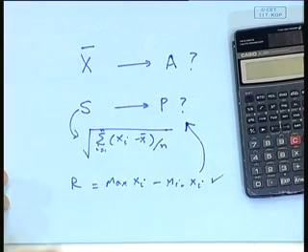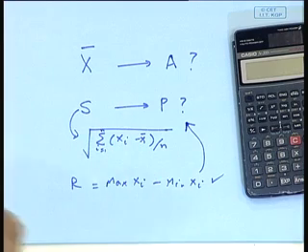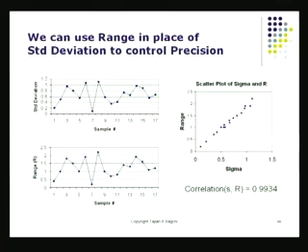What is the link between these two? You might just say then, is there a correlation between these two? Let's look at some real data. I have on the screen here, the top chart is the S chart, the standard deviation chart. I've got my samples here, I've got the values there. For the same data, I calculated range, and they are like this. And notice how close these two are. In fact, if you do a correlation plot between them, if you do a scatter diagram, that correlation turns out to be like 0.99 or something like that.